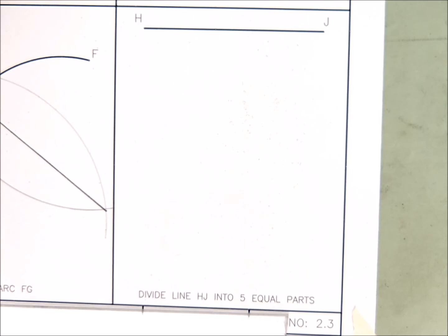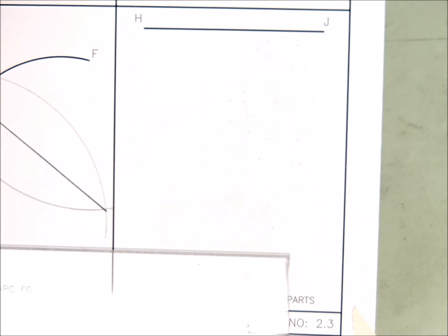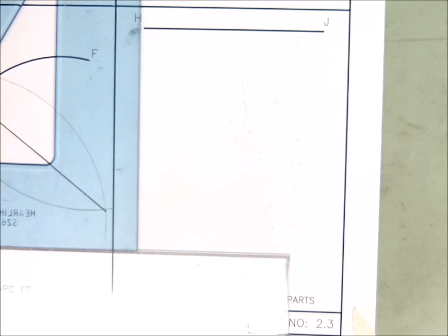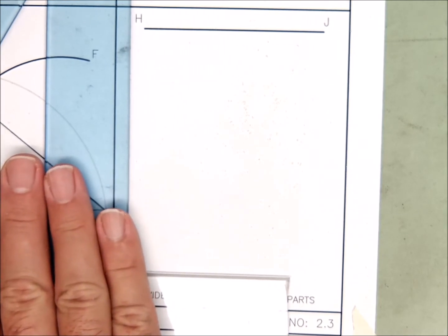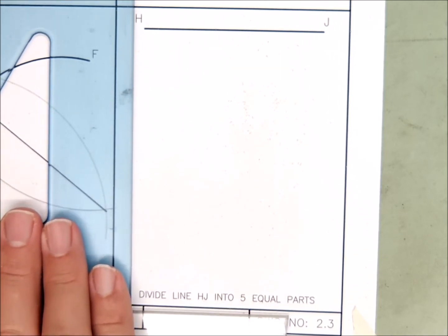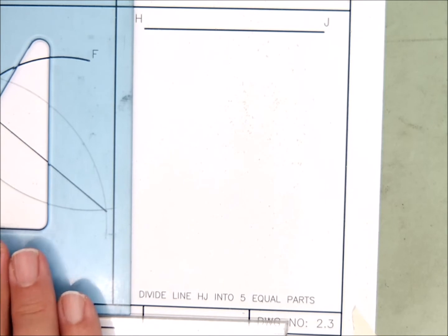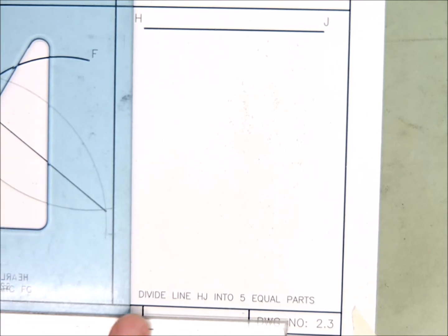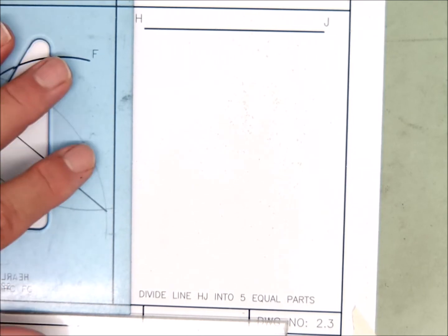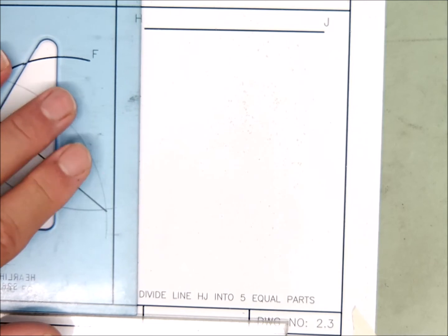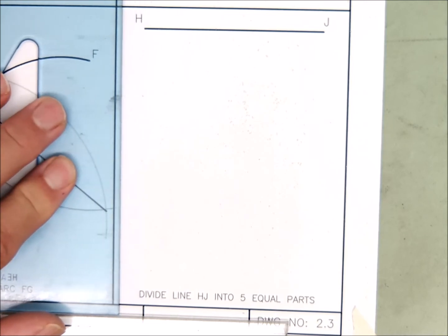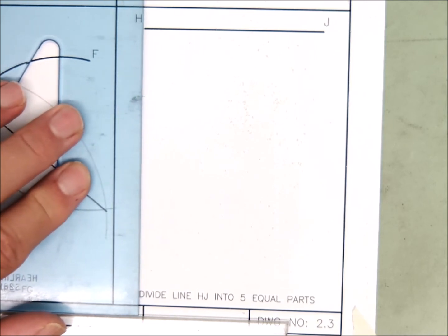And what we're going to do is put our triangle on top of the blade of the T-square, and then slide them down at the same time. Maybe one hand on the triangle, one hand on the T-square. Okay, so the T-square or parallel bar is right here, and the triangle is sitting perfectly on top of it. And then maybe you can use your non-primary hand to hold both of those so they don't move around too much, and so you can adjust the triangle.